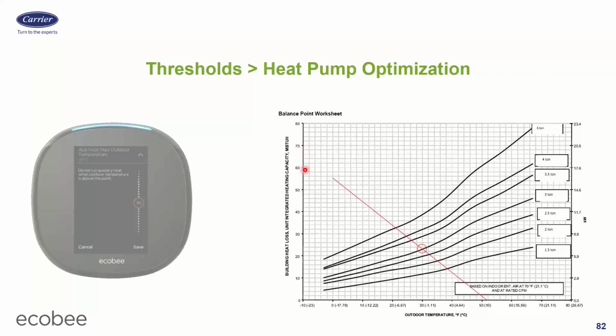And you figure out what your heat load is. So let's just say this is the Chicagoland area. My design temp is basically 0 degrees. And on my load calc, I needed 55,000 BTU. So right there, boom, that's my line. I draw it on a 45-degree angle down this way until it hits the other line. So this is the load line of my house.